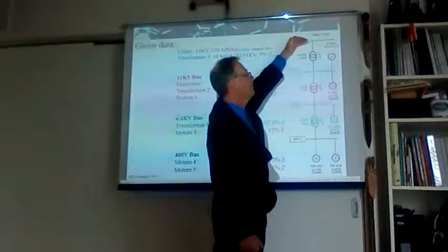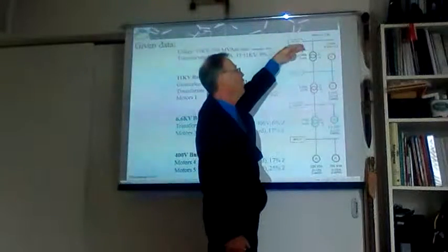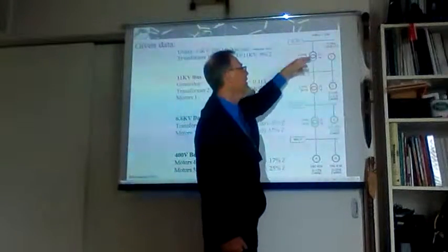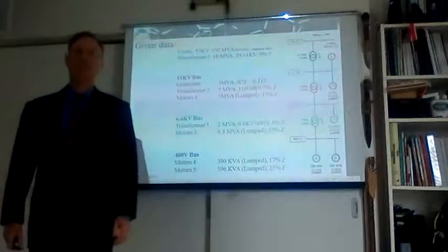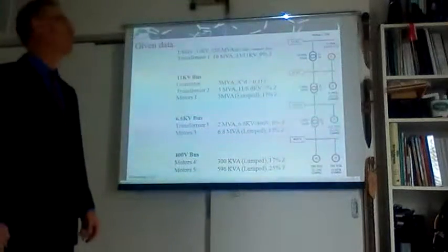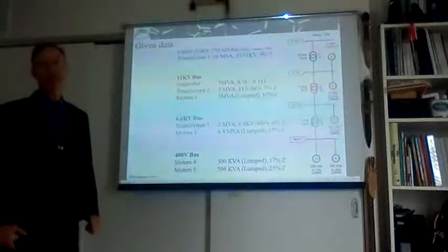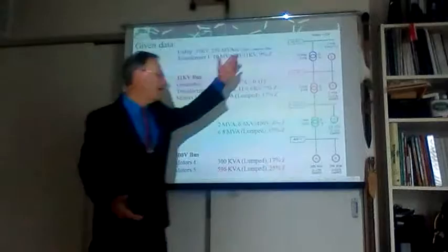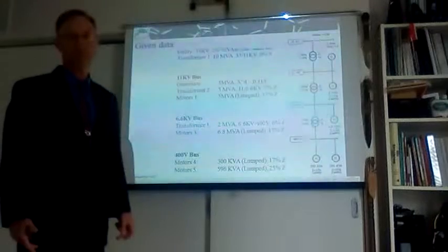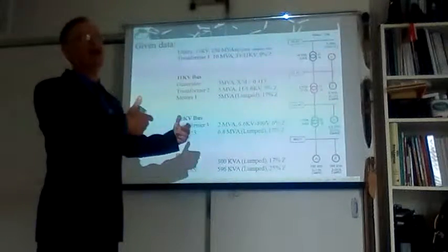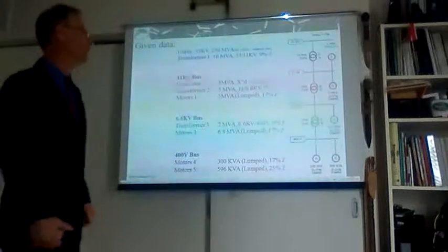The main line, the top line, is a bus that will see only the primary of the transformer sitting here, the 10 MVA transformer, which is in this case 9% internal impedance during a fault. Each one of them, in case of a short circuit, regardless of where the short circuit is, will respond differently. And it is based on its MVA size and its internal impedance.